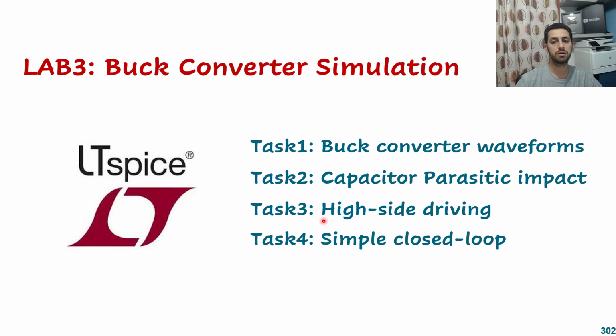And then we will discuss the high side driving. We know in the buck converter that we have a MOSFET which is considered the high side MOSFET. So how are we going to drive it? Is it by just sending PWM straight away to the gate, or is there some other configuration that we have to discuss? I think I covered that in the lecture, but today I'm going to implement the bootstrap and also another topology to show you the challenges of driving high side MOSFETs and also what the solutions are.